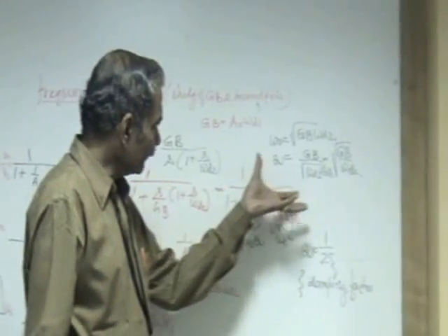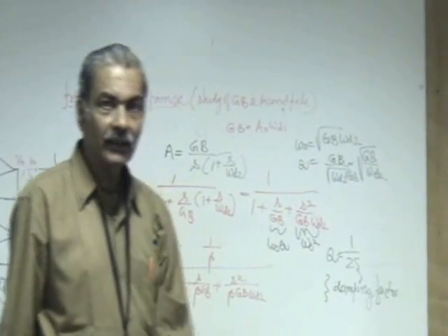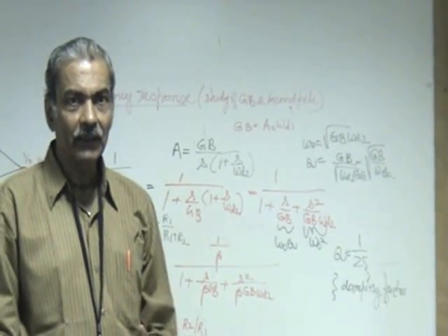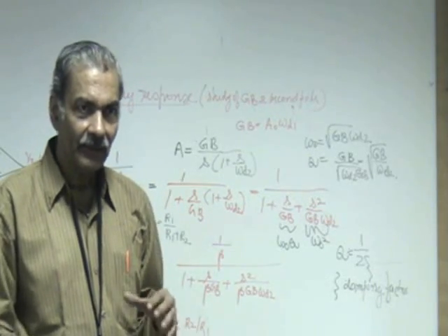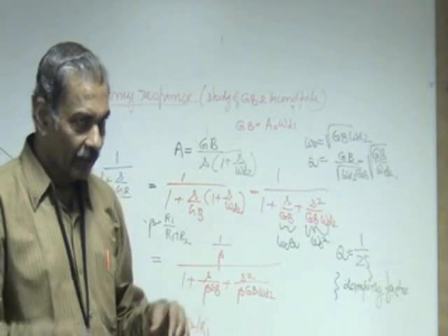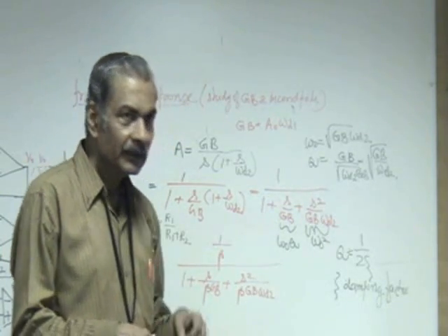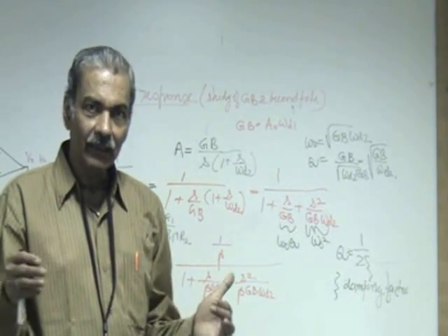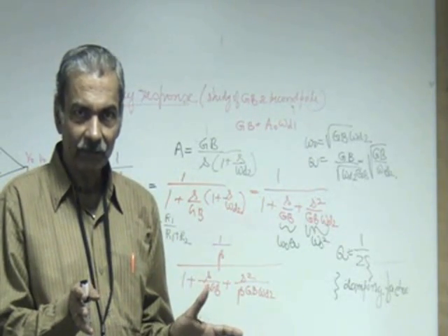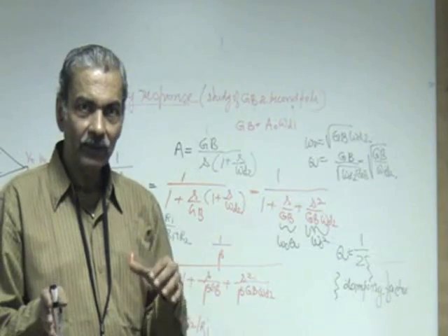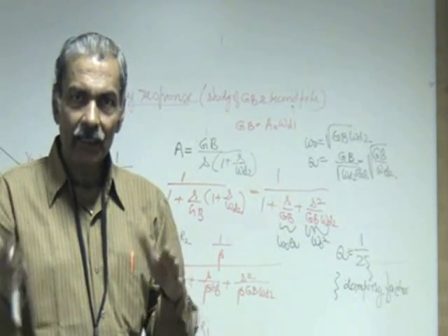Now that we know that, Q of this system can make it very transient, noise dependent, so that when a step input is given, it will start ringing, and the ringing frequency will be close to the natural frequency of the system, and Q is going to tell us how many such peakings will occur in the ring.